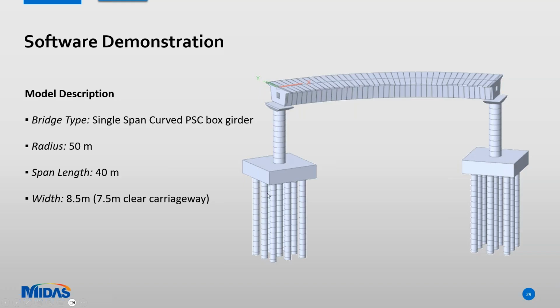And then there is another plugin which we are going to use, that is the group files. Again, we're assuming this particular pile cap, whether you want the pile cap as a line element, or you want the piles directly connected by a rigid link without considering any stiffness of the pile cap. That way also we can model using these plugins.